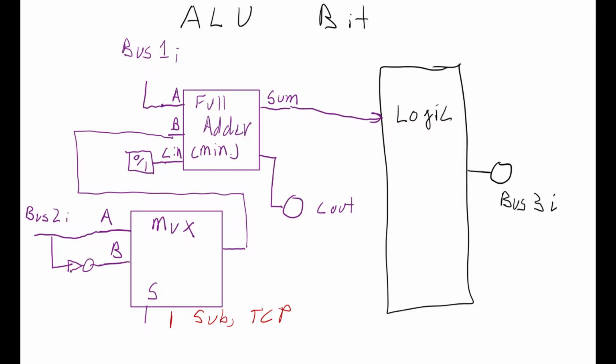So we want it to be high, and it should be a low voltage on any other operation. Okay. Now you can draw up a truth table and figure out a Boolean logic expression that has inputs for subtracting and 2's complement, and when they're on, you want this to be a high voltage. Although you might not need a truth table because the logic is really simple.